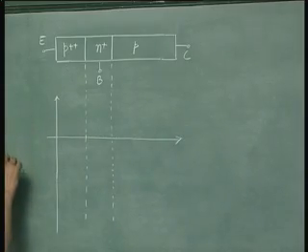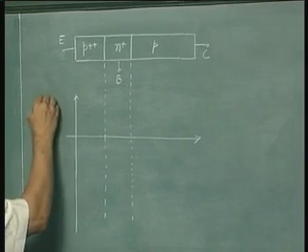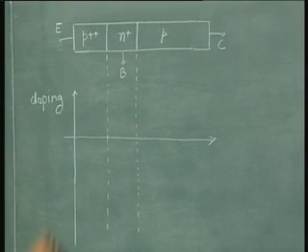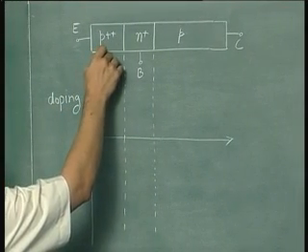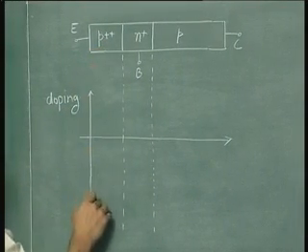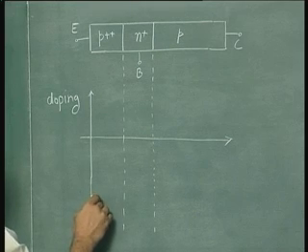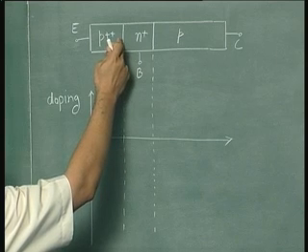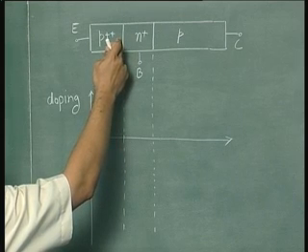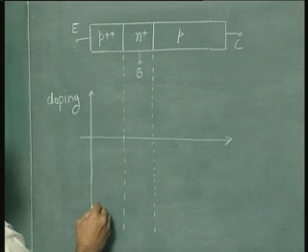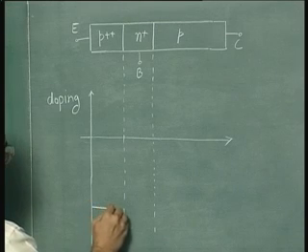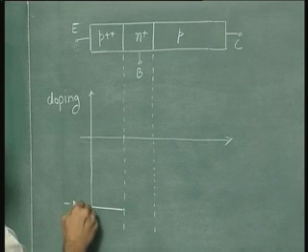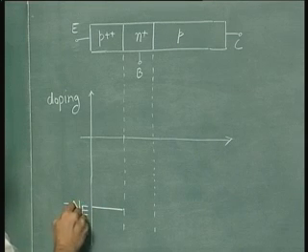So if the doping profile is shown here, it would look something like this. We will show the acceptor type doping on the negative side, simply because in the space charge region near the junction, the acceptor type doping leads to a negative space charge on the p side. So let us indicate the doping here. We will call this the emitter doping and represent it as N_E.